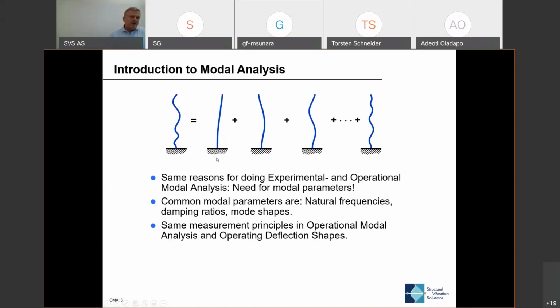The most obvious one to look at is the mode shape. So the mode shape of the first mode is a very simple one that is, in this case, only a bending back and forth like this. Along with this mode shape here, there will also be a natural frequency, and there will also be a damping ratio. So there are these 3 parameters that are describing a single mode of vibration, and there will be many of these. There will be a whole bunch of them that has been excited due to the excitation that we have supplied to this structure here.